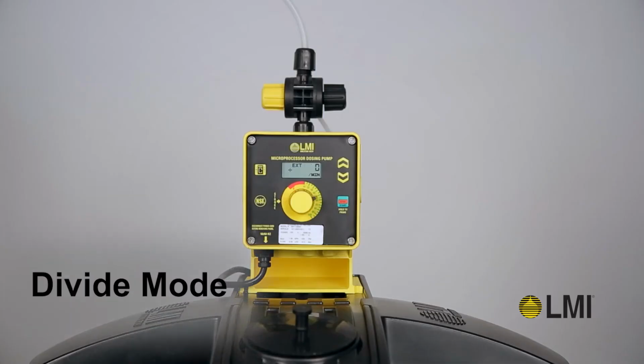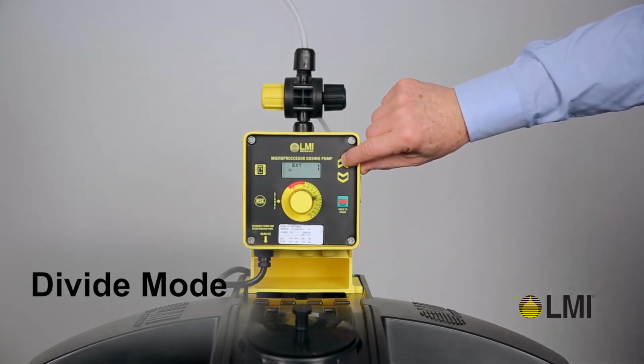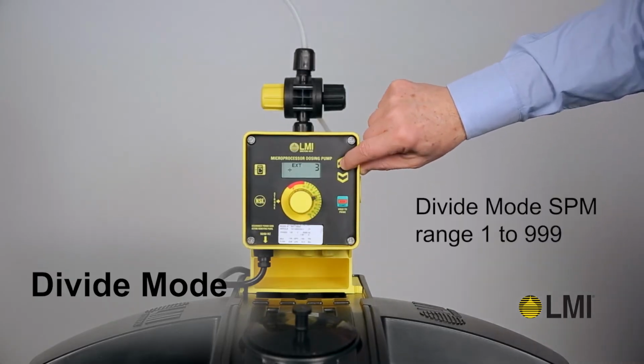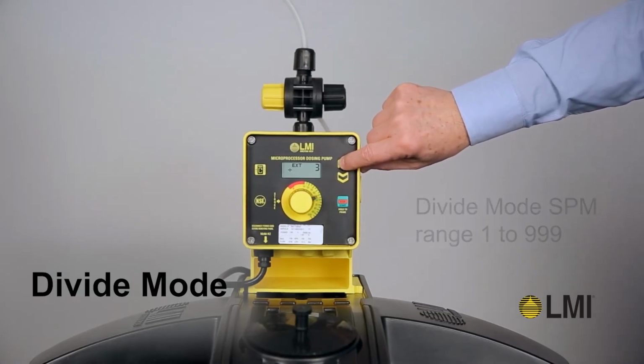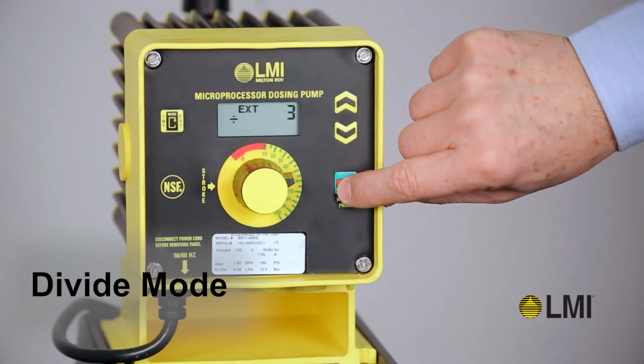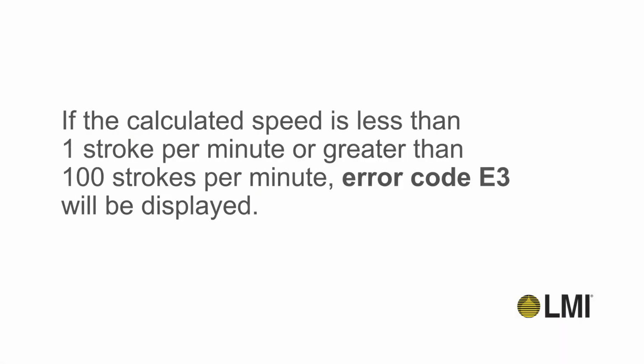When in divide mode, use the up and down keys to change the value. The range in divide mode is from 1 to 999. Press the start/stop key to start the pump. The pump symbol appears on the screen. The pump is now ready to receive external signals.